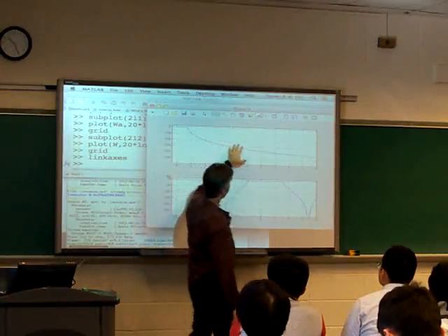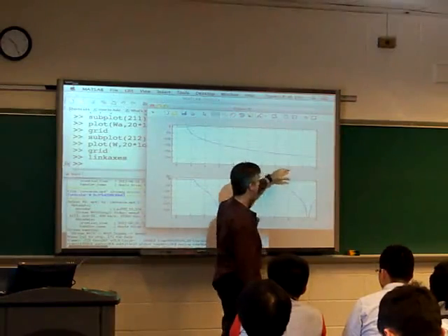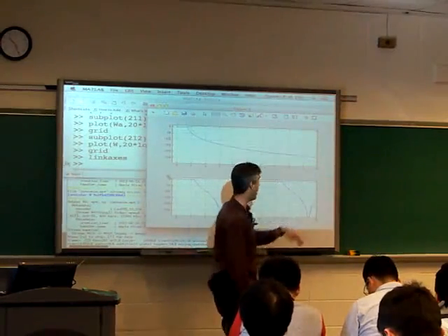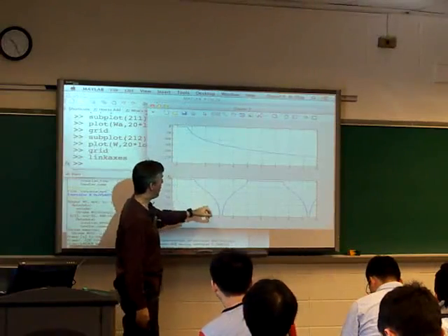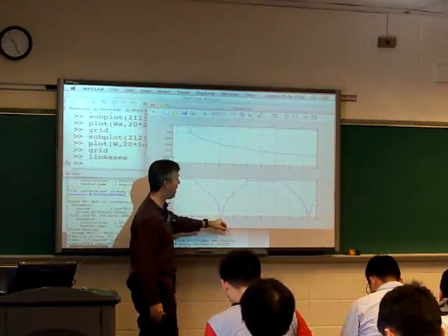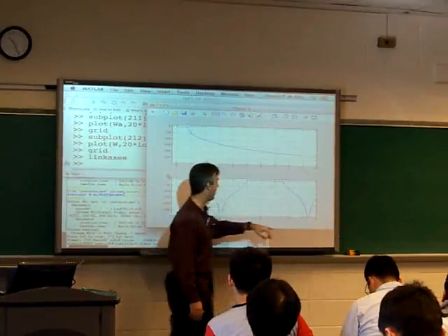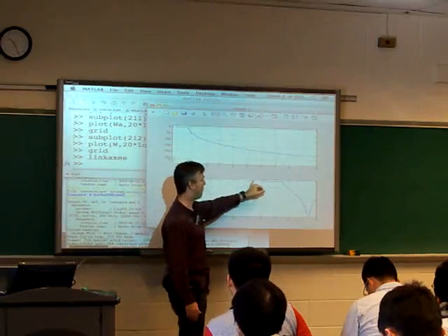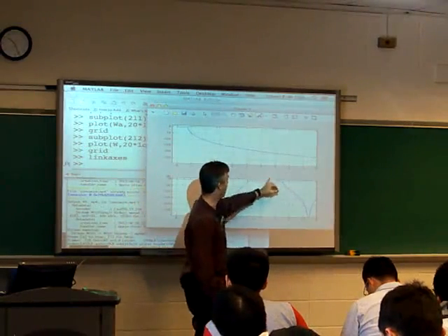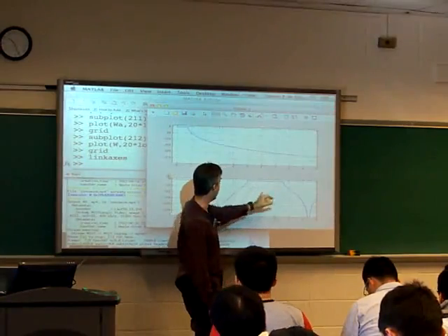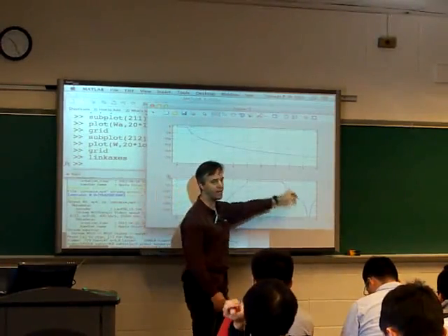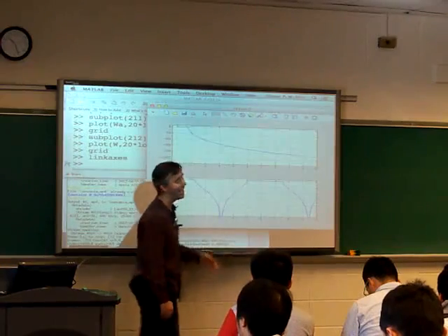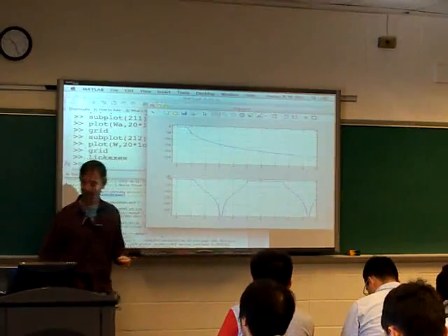But here, for the continuous time one, we can go up to whatever frequency you like. It's going to keep going down. Here, for this discrete time one, now I plotted it not just up to pi, but up to some factor of pi, and we see that beyond pi it starts repeating, and so we get the whole thing. This is the alias around 2 pi here. It's the alias around 0, and then it goes down again, right? So clearly they look very different in that respect.